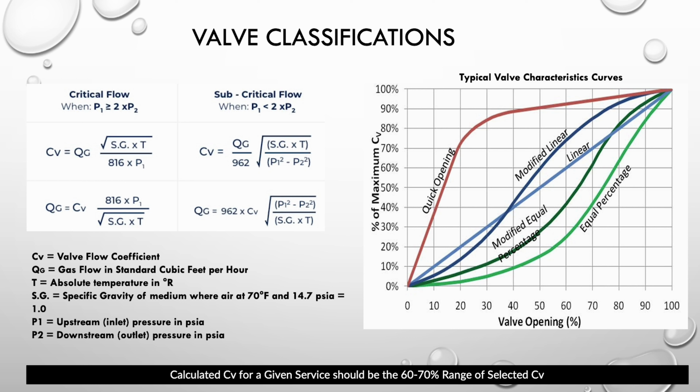engineer or the process consultant, which is basically reflected from how sensitive a given, for example, reactor is to change of your main variable. Sometimes they will come back and basically say, hey, I need this delicate balance, where between 0 and 50%, I need it to be acting like an equal percentage. And then once it jumps beyond that, I need it to be acting quickly.